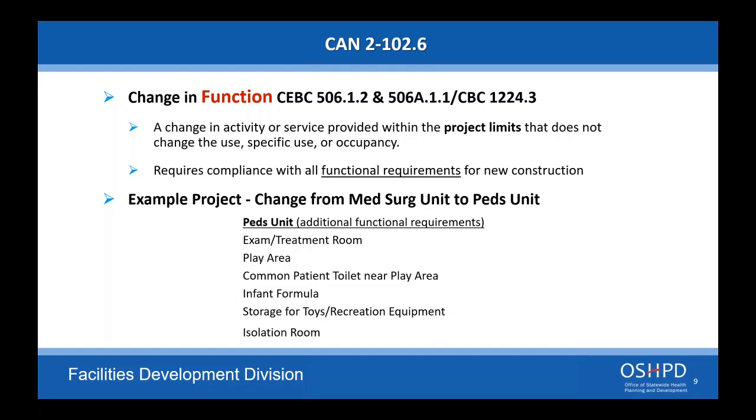A lot of the times with the temporary equipment, it's not known up front what the exact logistics are, and those are done oftentimes separately during the project. It is not an ACD to the project. It would be a separate permit, but you can include it in the original project. If you know exactly what you're planning on doing, you can include the temporary work within the original permit.